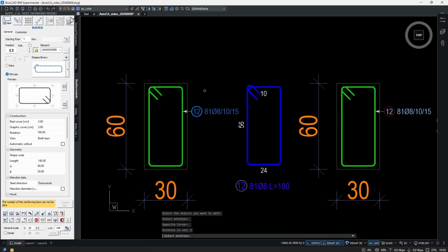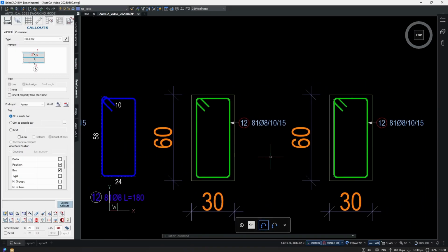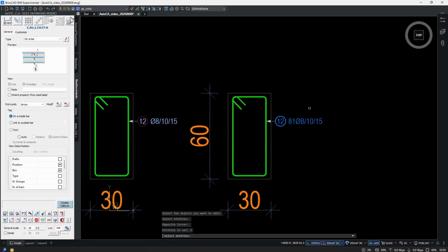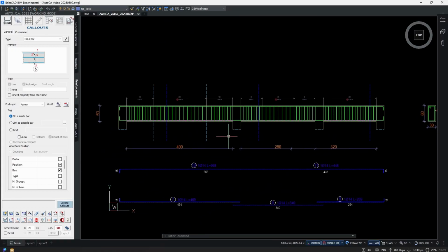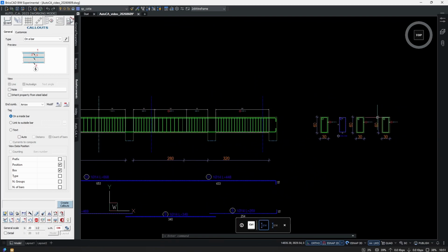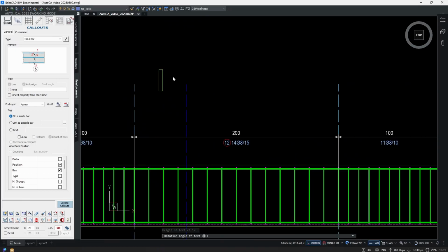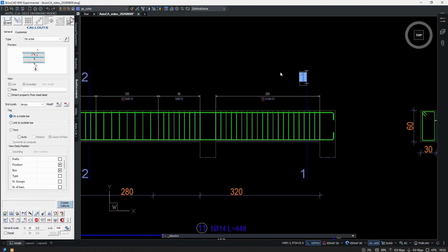The only thing is to disable the total bar from the callout this time, because it might confuse others if we have 81 bars on each position. So yeah, in my opinion, this is the right way to do multiple cross sections. I'm gonna give a number. The first is 1, this is 2, this is the third one.